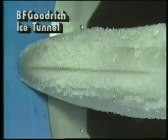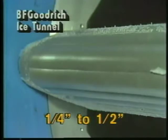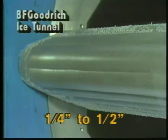While you should follow the manufacturer's recommendations as to when to operate the system, the general procedure is to allow 1/4 to 1/2 inch of ice to accumulate before activating a pneumatic system. If the ice is too thin to break away cleanly, it may refreeze, leaving a space between the ice and the wing. Further attempts to de-ice the wing may be ineffective because the boots inflate within the cavity and don't break the ice.